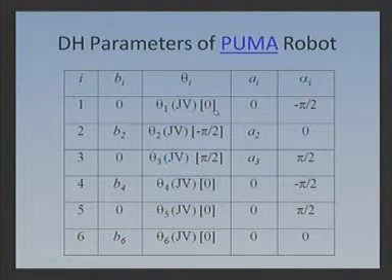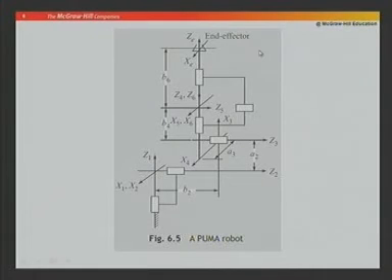What I have put here, 0, minus pi by 2, 0, 0, 0, it means they are the angles corresponding to the diagram I have just shown, because in the diagram we have to show a particular configuration of theta. So, at this point theta 1 is 0 and theta 2 is minus pi by 2, which means what? Theta 1 0 means x 1 and x 2 axes are on the same line.